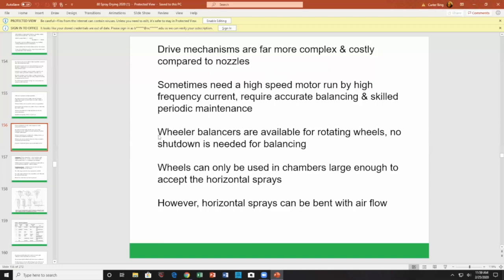Yes, a wheel balancer can balance your wheel and protect your bearings. However, after a while, the buildup could be so substantial that the next failure could be catastrophic. In other words, the wheel balancer will give you a sense of complacency and let problems grow, and they grow. And then voila, you have a major shutdown where the wheel balancer no longer can do the job.